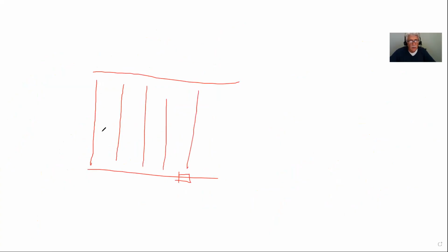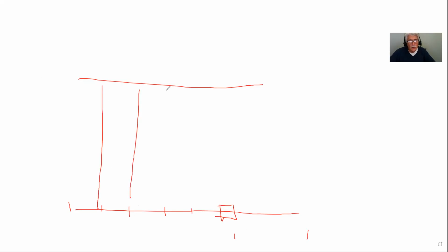You're going to have 5 of them, 2, 4, 6. I'm missing one. Okay, I should draw this properly. Clear all drawing. So here's my column, here's my Gerber girder, here's a cantilever of whatever it is. Okay, so here's my open web steel joist. You're going to show your open web steel joist here. And on your drawing, at this point here, you're going to put a little asterisk. Not here, sorry, I'm drawing the wrong one. Erase.